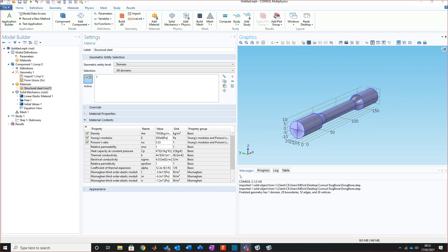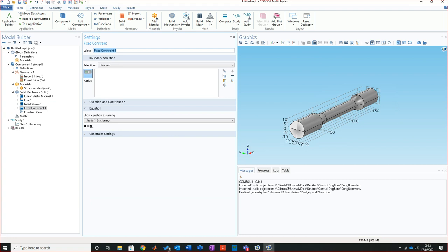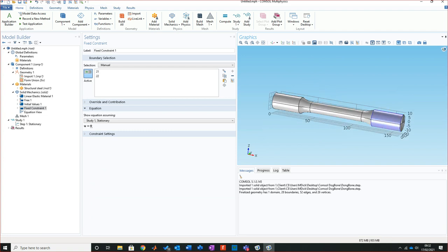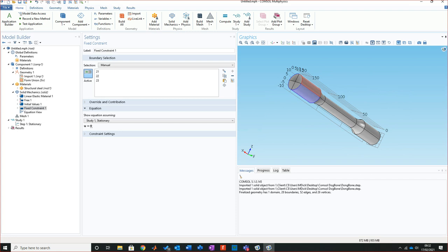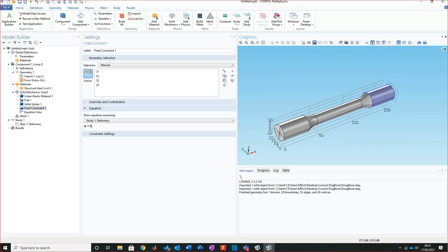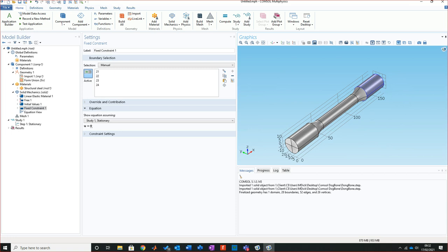Right, so again, getting back to it, moving relatively swift now. Right click, and I'm going to go to fixed geometry, fixed constraint. Under my fixed constraint, trying to replicate where this thing would be fixed, I'm going to click on here, and click here and here. So we've now got that back end constraint there, and that will be in essence where it would be fixed. And then what I want to do now is pull it apart like you'd get in any good reputable Tinius Olsen or anything like that.